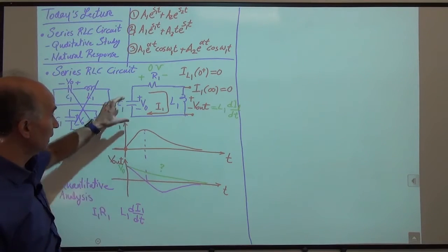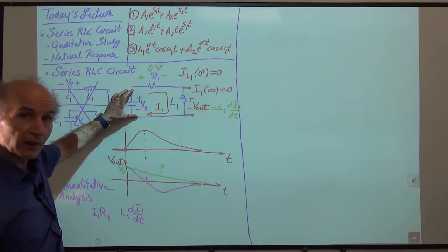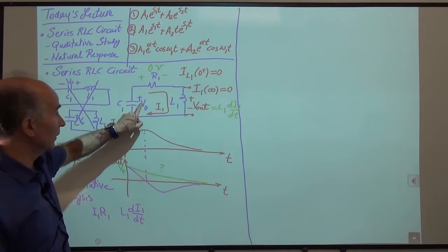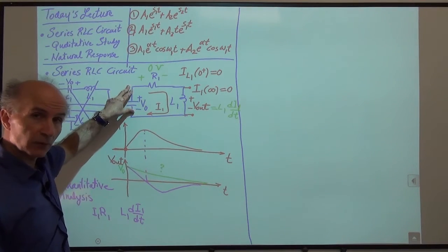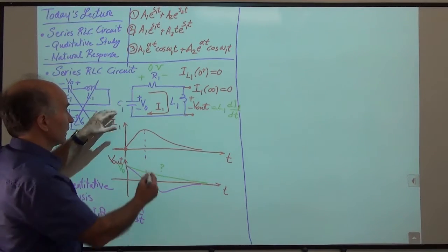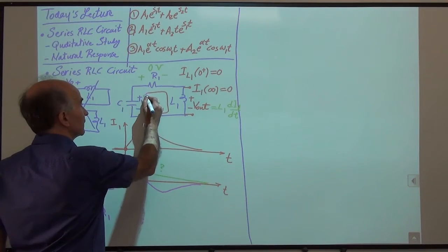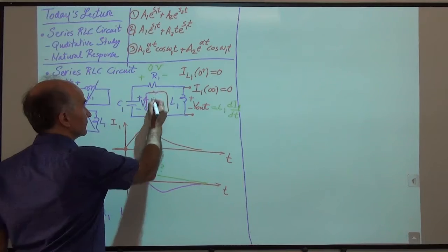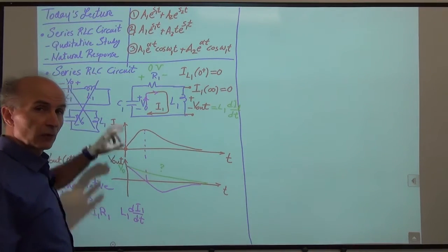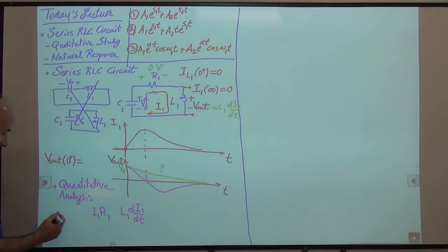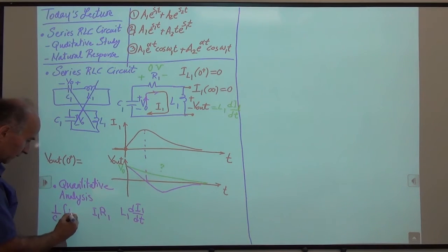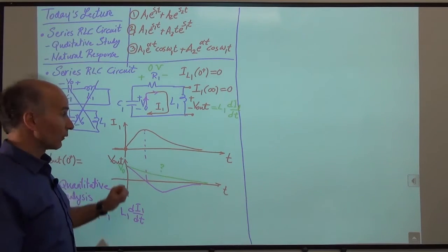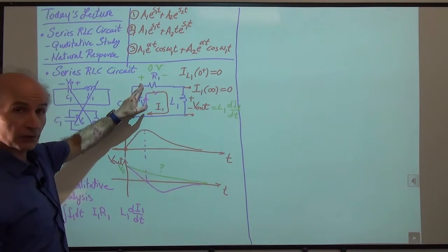And how much is the voltage across the cap? Well, if I have the current through the cap, which is called I1, I can find its voltage, right? So this current is going this way. You can see, right? So I can say the voltage on the cap, so I'm going to write that here. The voltage on the cap is 1 over the capacitance, integral of the current through it, I1 dt, except that the current is flowing from low potential to high potential, right?